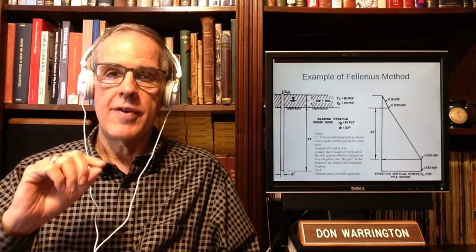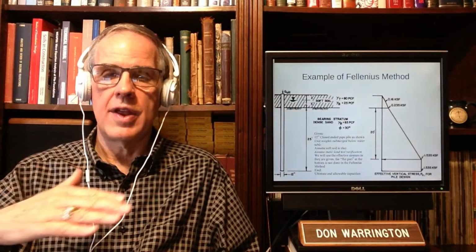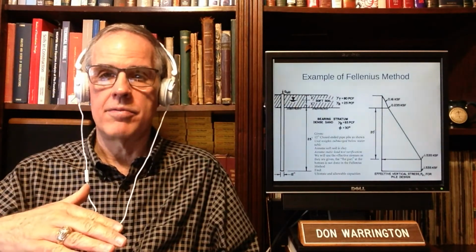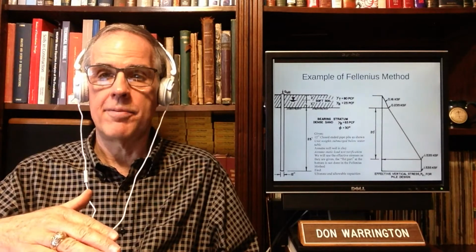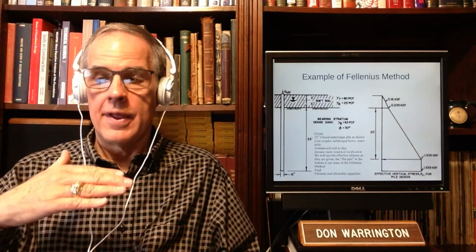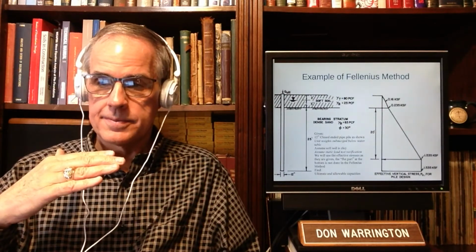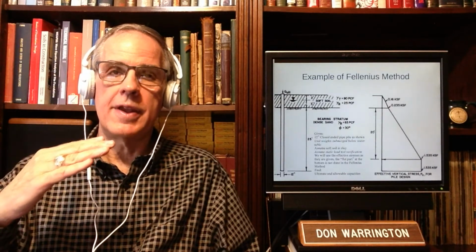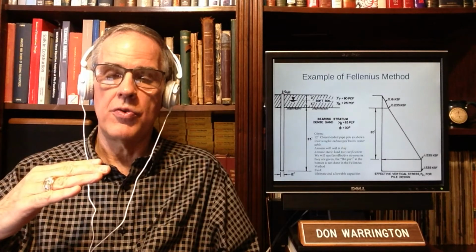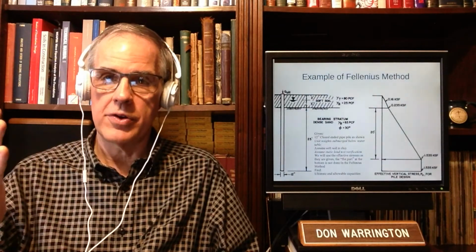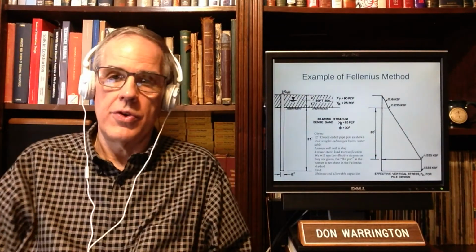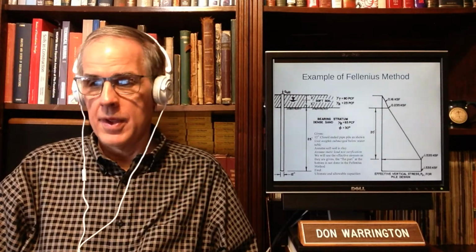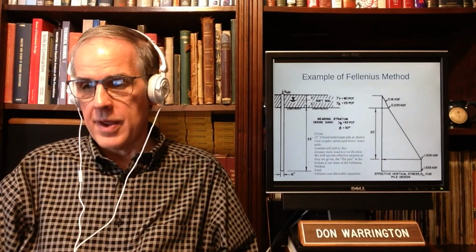It is one thing you must be prepared for, and we saw some of this in soil mechanics: when you have layers and you're given unit weights, and be thankful you're given unit weights because a lot of boring logs don't have them, frequently the gamma will be given to you as a submerged unit weight, not necessarily a total unit weight, and then you subtract the u from it. So be careful.